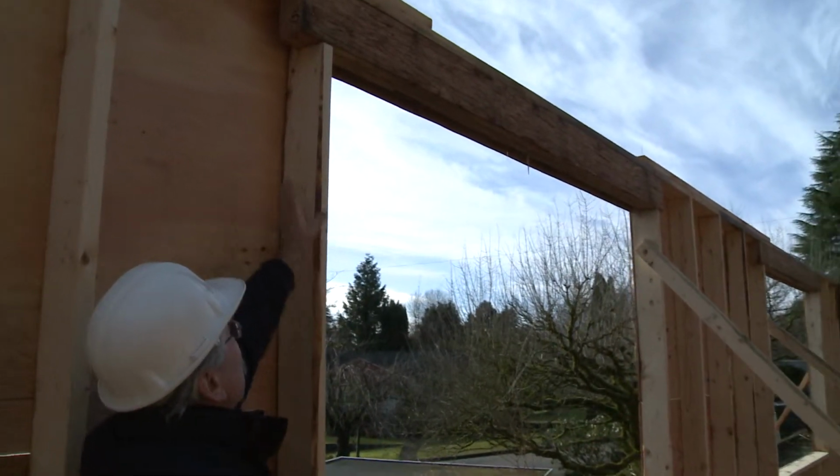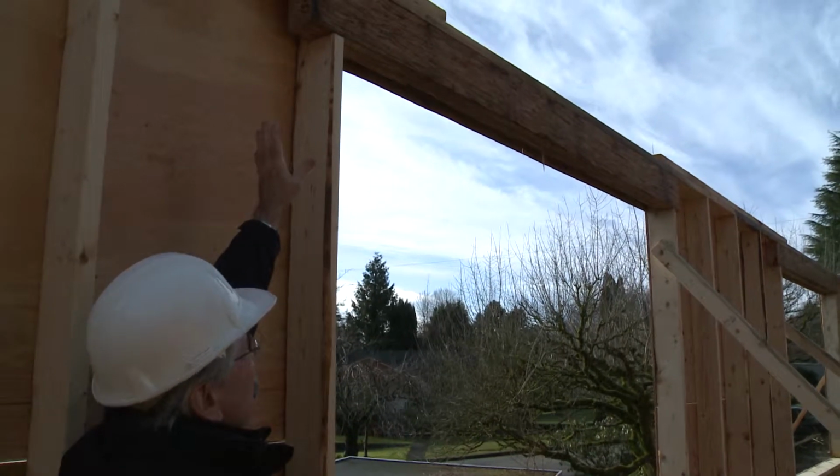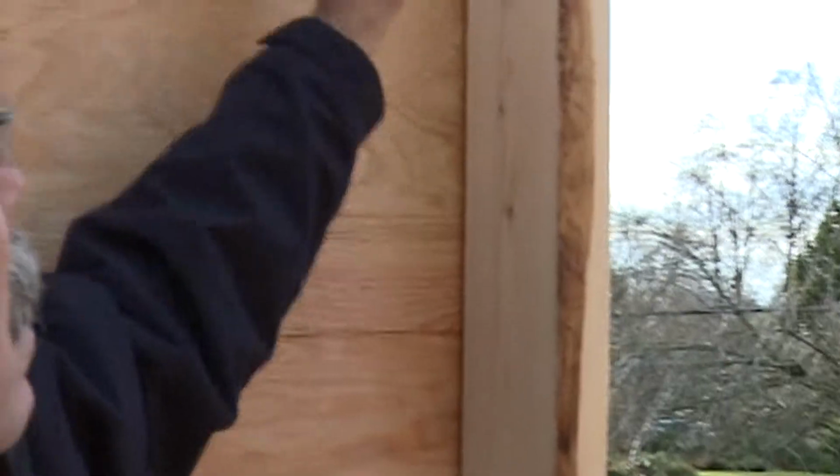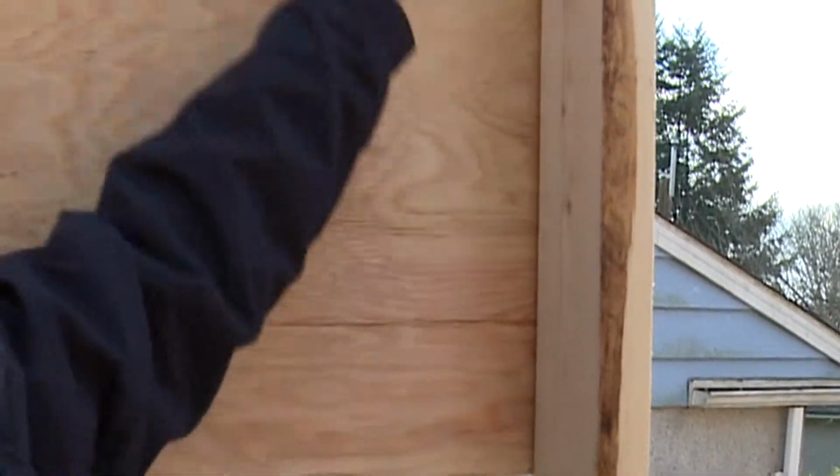Typically the studs are notched on either side of the windows, and we don't have double studs on either side of the windows, which is typical. So we're doing a whole series of things in the framing of this first floor to minimize the amount of lumber. We're probably saving 15 to 20% of the amount of lumber we'd normally have, and that lumber in turn is being replaced with insulation. So we're going to end up with a wall that's resource efficient in that it uses less lumber, and also more energy efficient in that it has more insulation in the wall cavities.